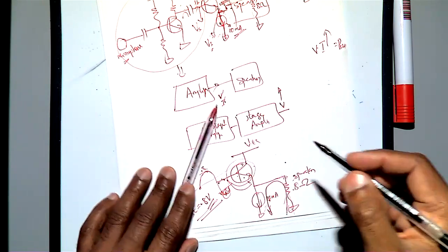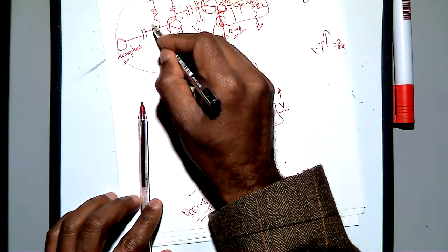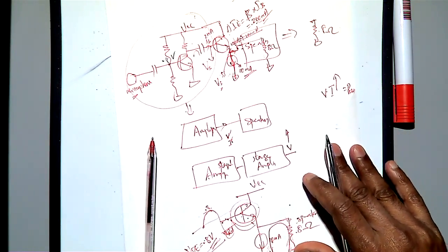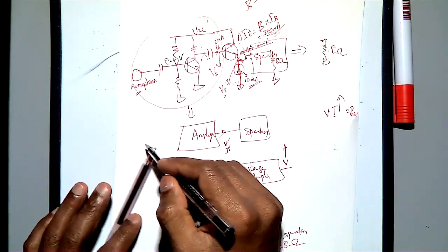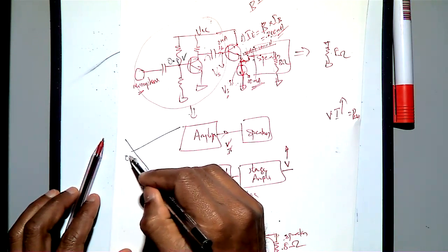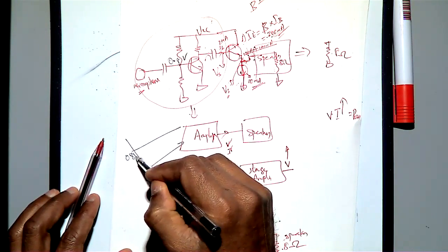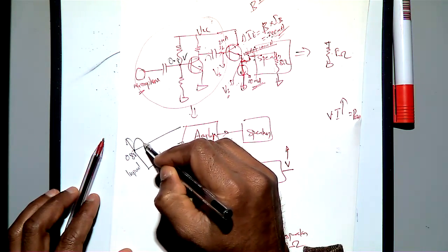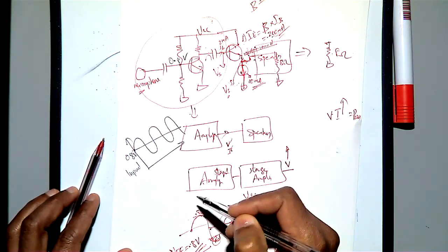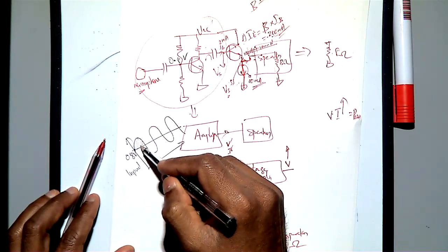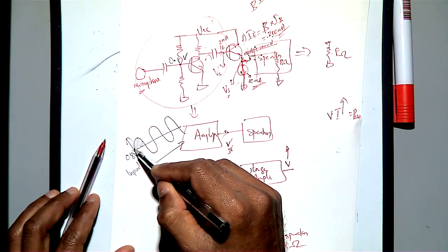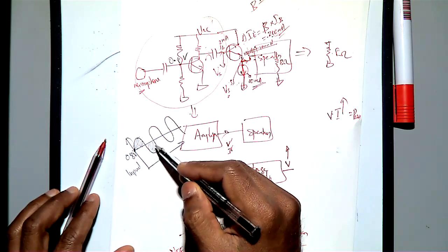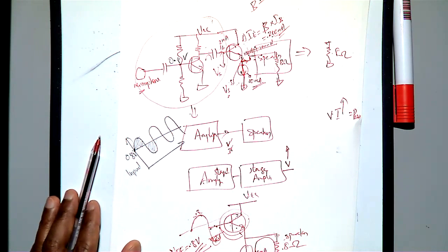So at the moment what is happening is here you got 0.8 volt. And then your signal rides on 0.8, and this is your input signal. Then the input signal is like this. So during this period your transistor is on, because your voltage is above 0.8 volt. But during this period is a problem, your transistor is off, because your VB is going below 0.8.